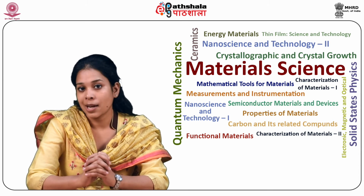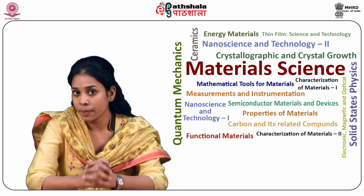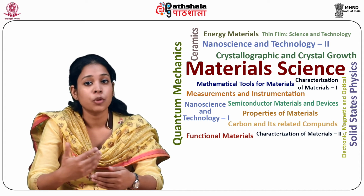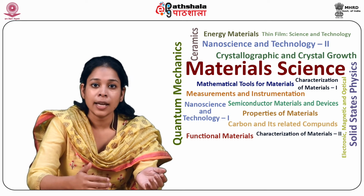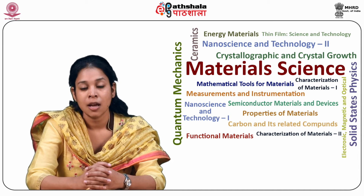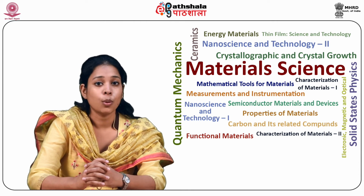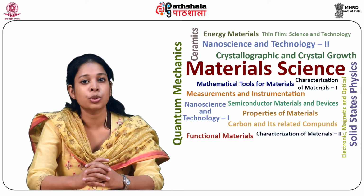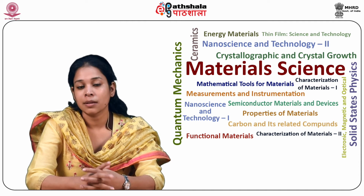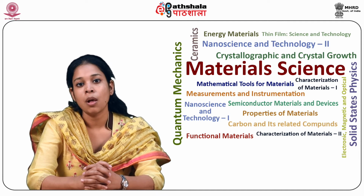Polycrystalline alumina has very good mechanical properties which make it useful as a structural ceramic. Because of its transformation toughening, zirconia ceramics can be designed to have very high fracture toughness, which is the advantage of this type of ceramics. Zirconia particles can also be used to toughen other matrices such as alumina, and these two structural ceramics are discussed in this module one by one.